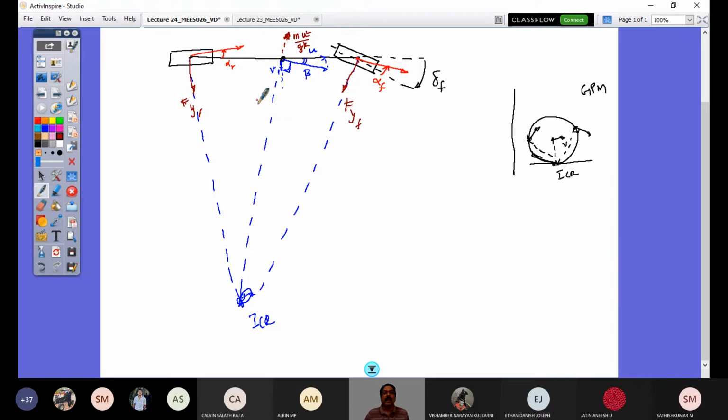So this is the free body diagram. So now you see these angles are very small angles. So if this is 90 degrees here, and if I have to resolve this force into two, one perpendicular to the wheelbase, this frame, other one along that frame if I take, and this force is very negligible, this force only I will consider. It is not negligible. When I take moment about this point that is going along with that line will not participate. So I would take a moment equation.